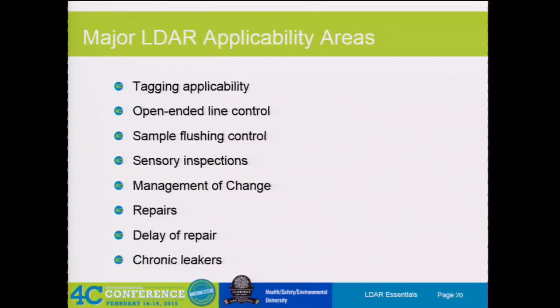Then you have sensory inspections. What's a sensory inspection? AVO. Yep. So that's anybody. Even if your operator's walking around and you hear something or you smell something, teach them to come notify you so that you can get somebody out there to see if it is part of the LDAR piece or something else, or, oh no, we're just losing steam, don't worry about it. Well, steam costs money to make too, so we'd like to get those fixed too.